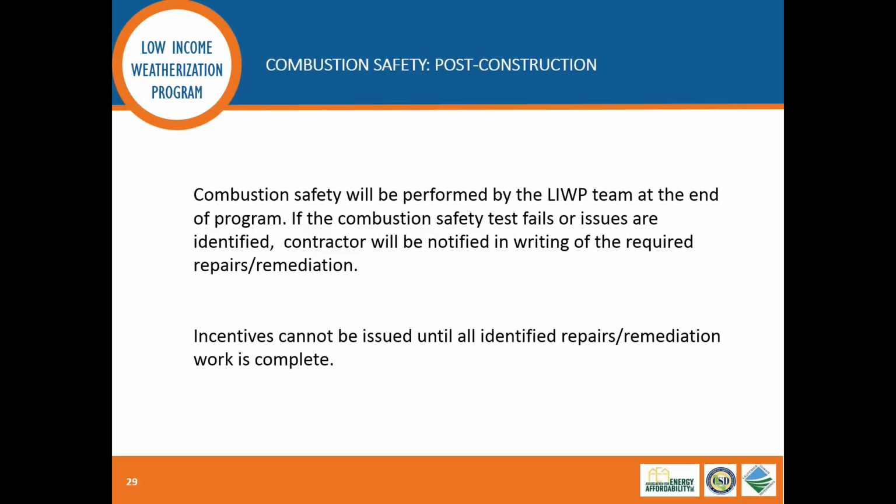So we're going to be going out there to make sure that the equipment's venting properly, that there's no gas leaks, that it has compliant gas lines, and that sort of thing. So we'll be working with the owner as well as the contractor just to make sure that we're all on the same page there. And then at the completion of the project, in addition to verifying the installation measures, we'll be doing some combustion safety testing to make sure that everything's safe. And if there's any issues that are identified either prior to construction or post-construction, we'll need to make sure that the owner addresses those before we can issue the incentives.